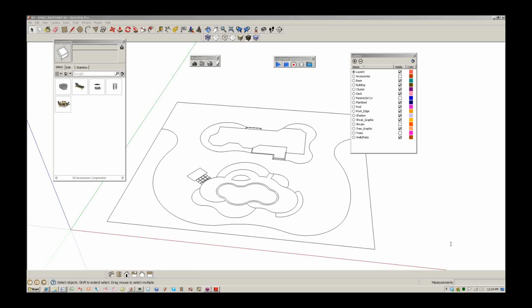So Amanda, you don't want to open the Ruby script once you've pasted it into the plugins folder. Just go ahead and open up SketchUp. Let me emphasize that the Ruby script is not something that you're going to open. It's going to automatically be in SketchUp once you have it. So just go ahead and open up SketchUp again, and you should be okay if you pasted it in there.